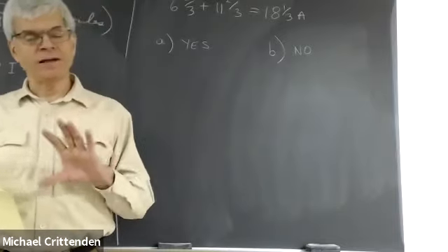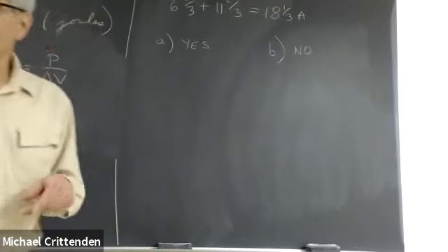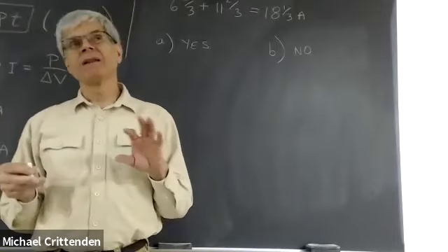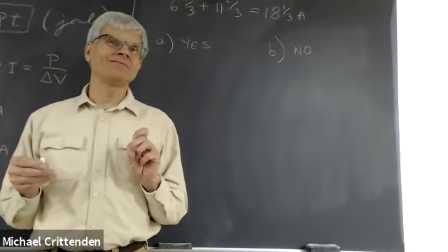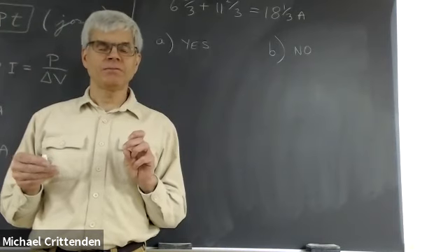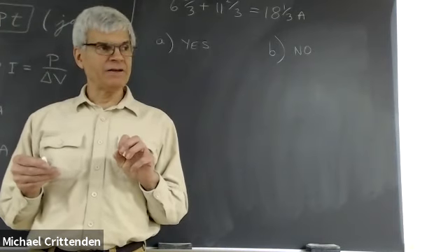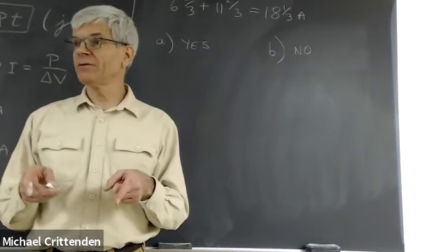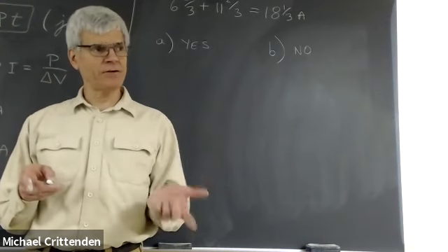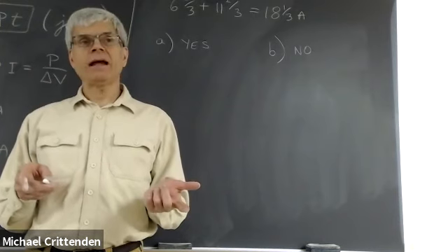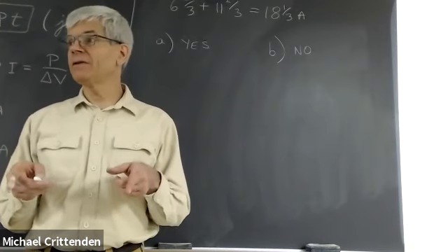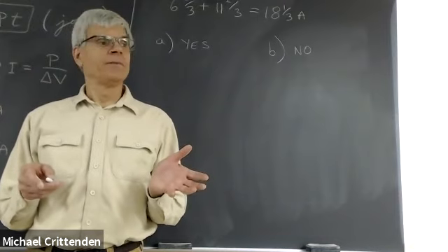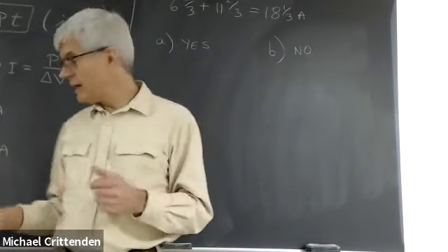Let's just say the voltage of the battery. Why don't you just call it that? Well, that's a less precise term. Someone could very easily take that to mean how many volts are between the terminals of the battery. And as you saw the other day, that is often less than the EMF, even for a healthy battery. It all depends on how much of a load you put on it.